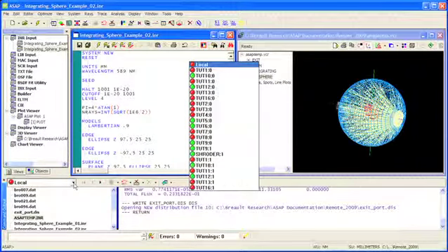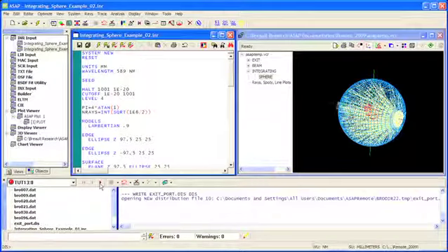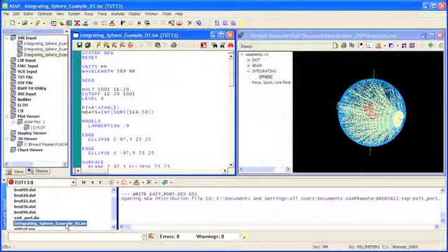We can check in on our progress and see that many of our sessions have completed and the rest are coming along nicely. Once all remote sessions have completed, we can again access each individual session to review and retrieve our results. We can copy any file to our local working directory by right-clicking the file we want. Since all sessions we've started are still open, we can also make changes to the individual scripts for any session and hit Run. We literally have 50 copies of ASAP available to use as we wish.